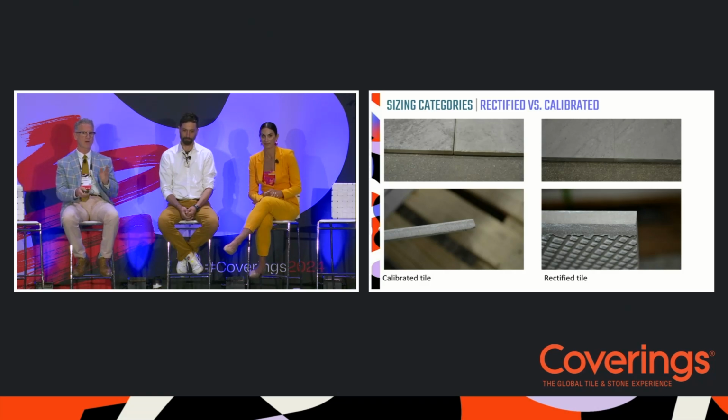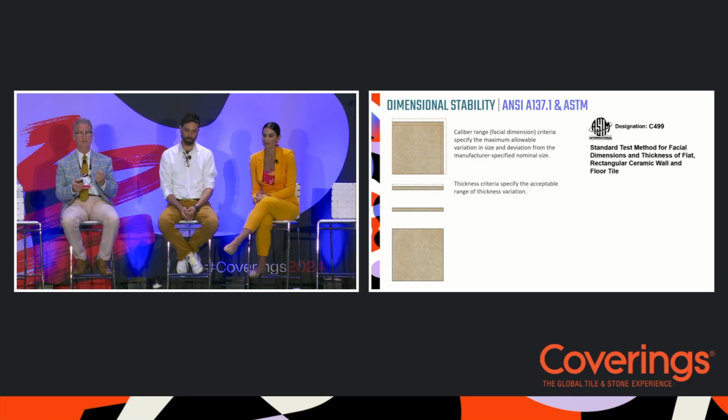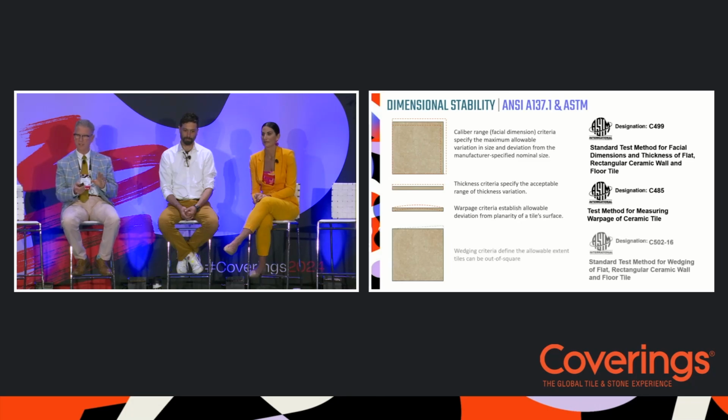So with calibrated, you're always going to vary a little bit more than you will with the rectified tile, as illustrated by that top example. Right? Manufacturers, in other words, are allowed to provide you a tile that's a little smaller or a little bigger than what you expect it to be. Okay? Same is true with thickness. Same is true with flatness. Tiles are allowed to be warped, not by a lot, not by the amount that you see on the slide, but you get the idea, right? And tiles are allowed to be a little bit out of square.